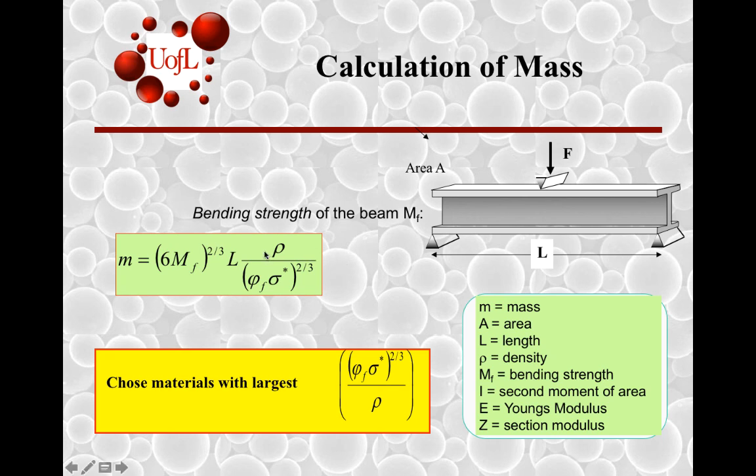There are ways to empirically, that is experimentally, calculate the shape efficiency factor for various situations by rearranging terms, where if you move phi f over here and you know all the other attributes based on the load, the mass, the dimensions, and the material, you can estimate the value of phi f for real life situations. It can be anything from a bridge, which is a very complicated structure, compared to this small I-beam over here.